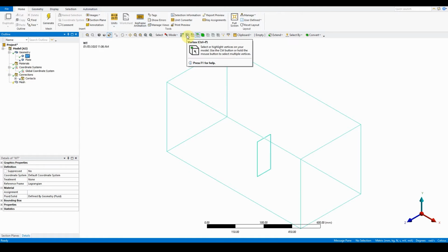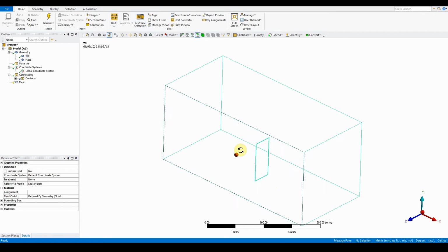Very similar to the Design Modeler, we've got vertices, edges, faces and volumes. Whilst there's no mesh on this model, it's the best time to select faces so we can give it a name selection. What a name selection means is we're defining what that face represents in the fluid dynamics part of the package. Again, the mouse buttons are exactly the same.